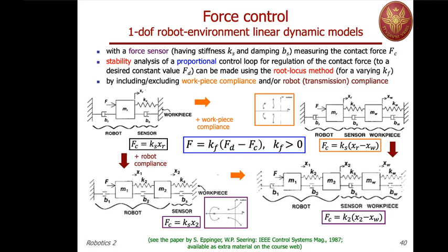So in the transfer function between F and the controlled force Fc, which now takes a different expression, you can recognize this by yourself. There will be 6 poles which are stable in the open loop, but once you increase the gain, you will get again instability.